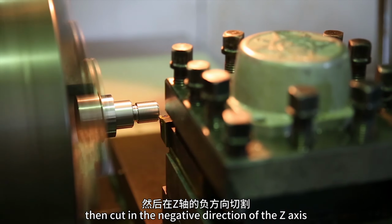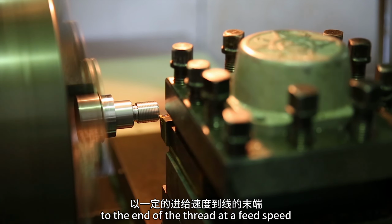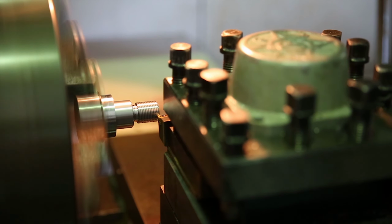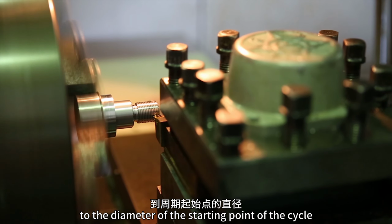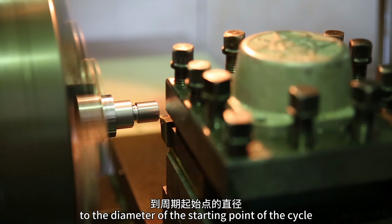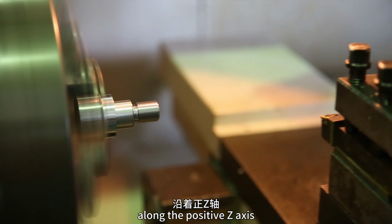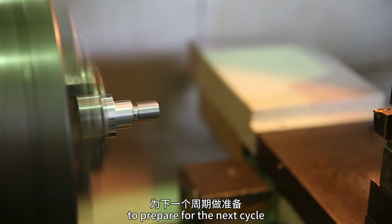Then it cuts in the negative direction of the z-axis to the end of the thread at a feed speed, moving 1 lead distance per revolution. And the tool backs along the x-axis to the diameter of the starting point of the cycle. Finally, it returns to the start of the cycle along the positive z-axis to prepare for the next cycle.